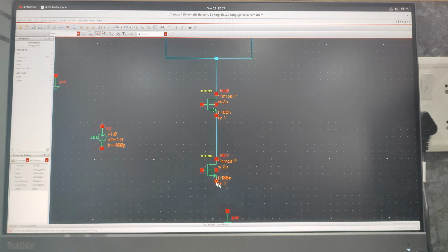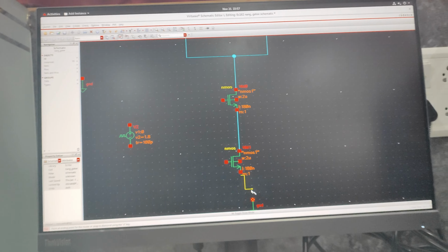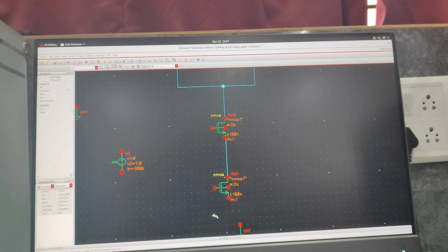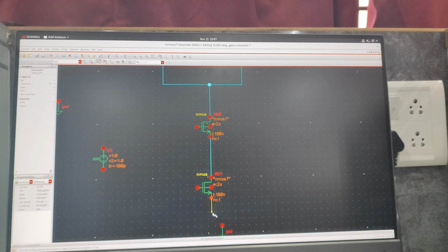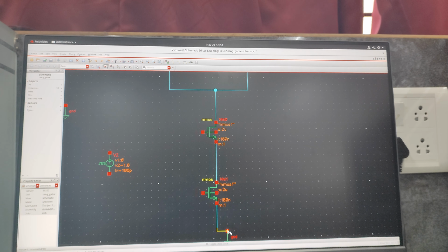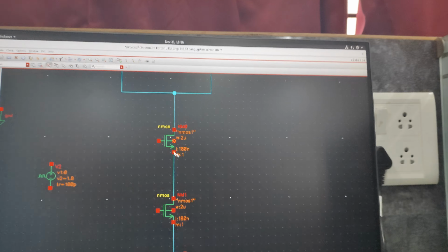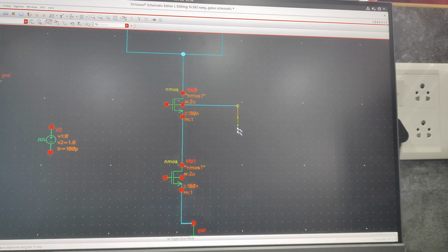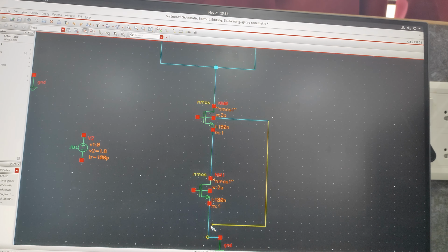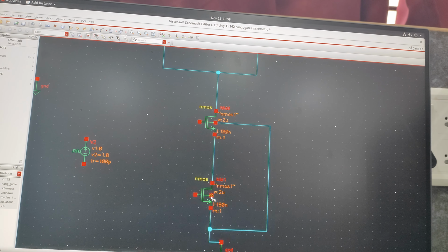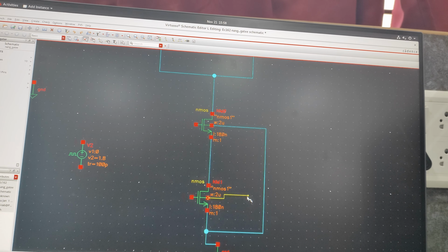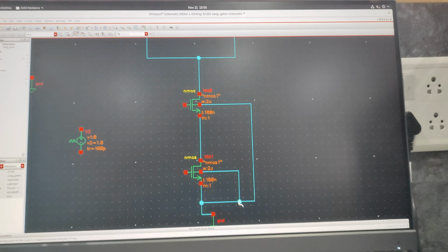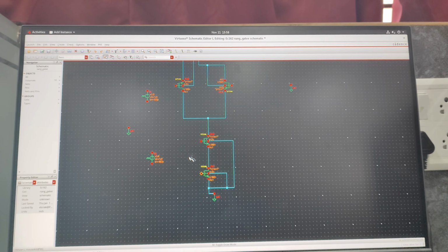So from this point of the PMOS, see, I haven't selected that point correctly. Escape, again W. Click on this point, it will come down and connect to this point of the ground. So the center point of the NMOS, get it separately and connect this one along with the ground. Similarly, this one will come to the ground point of the wire. Okay, so the NMOS and PMOS basic circuiting is done.